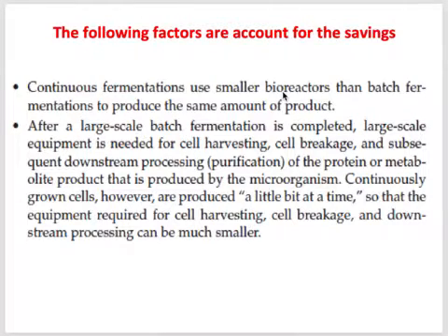And another one: in batch fermentation, as we have to use a big fermenter, every machinery that we have to use after the fermentation has to be big, such as the cell harvesting equipment or the equipment to break the cells. Also, in the batch fermentation, we have to ferment a big amount of substrate, right? That means after the fermentation, in the purification process, we have to deal with a huge amount of fermented product. So it will increase the cost.